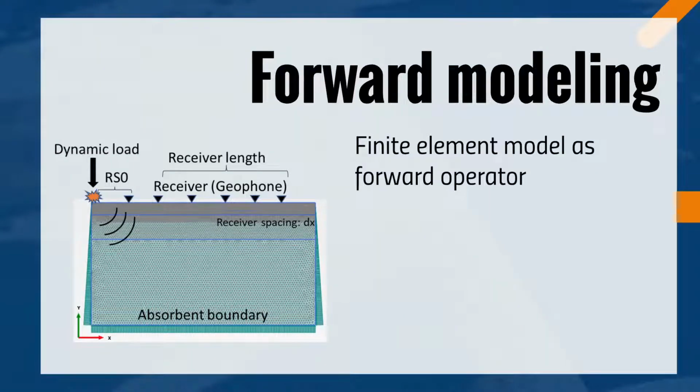The partial differential equation system is established to simulate the wave propagation in a solid medium. We use the finite element approach to solve this physical problem as a forward operator that discretizes the model in spatial and time domain. We then extract the theoretical shot-gather that follows the in-situ acquisition parameters, calculate the dispersion spectrum, and compare it with our field observation.